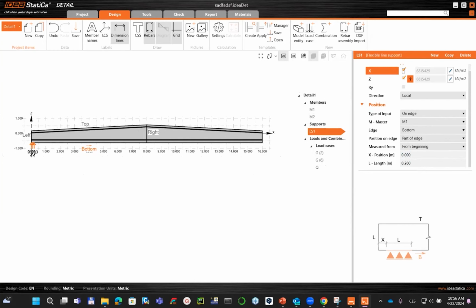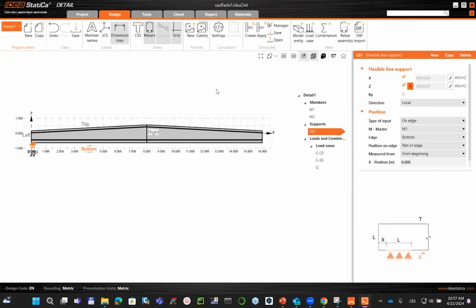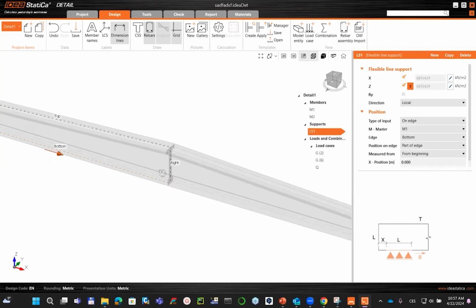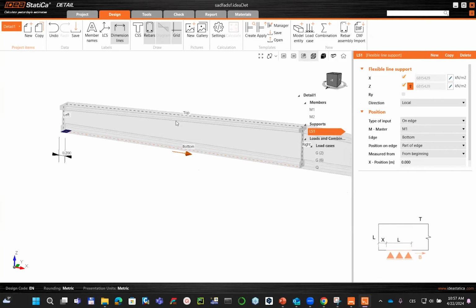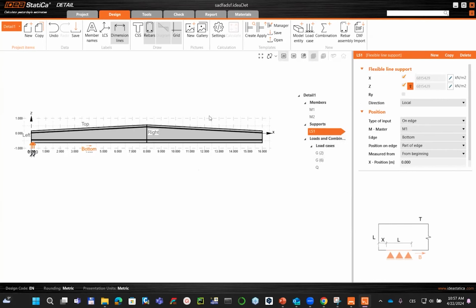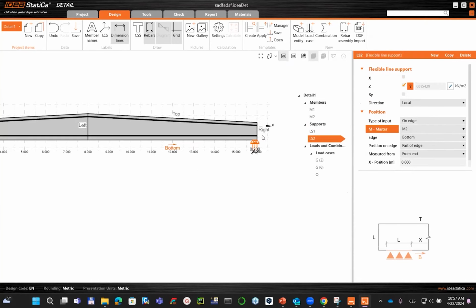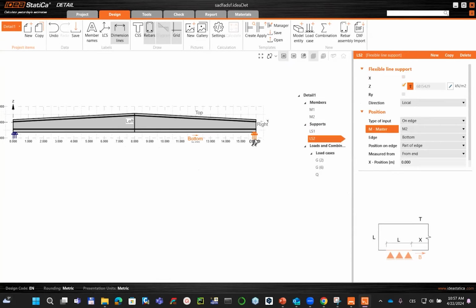Right now, we have a model that is composed from, let's say, 3 walls. Yep. So be careful. It's a wall model. It's not a 1D beam element. So I will copy this operation. I will just change it, release it in the longitudinal direction and measure it from the end, but from the member M2. You can see I have created very swiftly the boundary conditions.